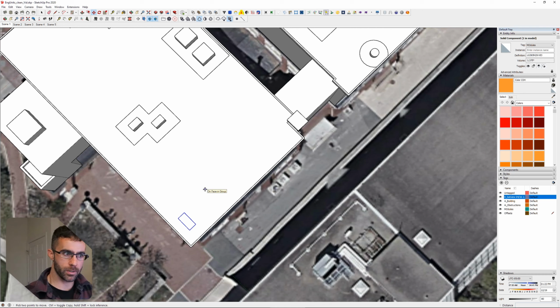The first iteration that I usually go through is parallel and perpendicular. I don't know why. It's kind of a 50-50 whether you can fit more panels in a parallel and perpendicular configuration that will offset the slightly decreased production numbers, or if it makes sense to fit maybe fewer modules on the roof but have them slightly more optimized for production by facing north or south.